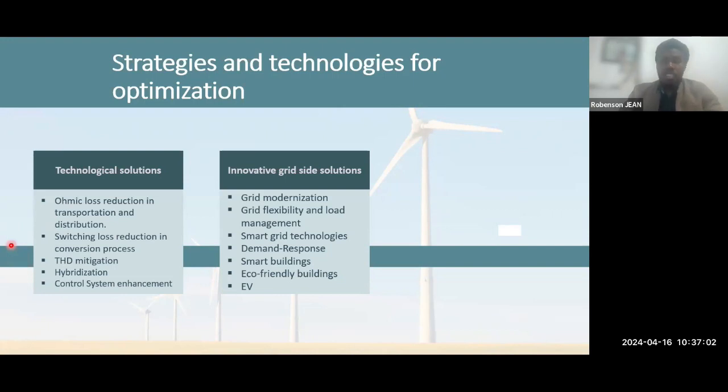Also, we have the load management. The load management is like a temporary shift in the electricity demand. So it helps also. It is mainly scheduling loads in order to reduce outages and understand the peak load demanded nationally and within a geographic hierarchy for operational purposes. So this helps us to give better services on the grid side.